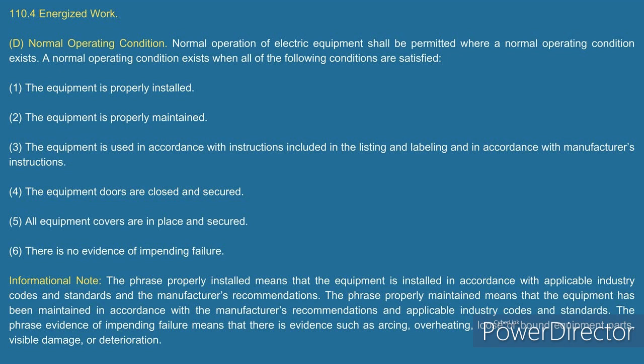But you're not opening equipment, you're not doing anything. Sure. You have to realize how serious that is. I was up in Seattle looking at the safety for Nucor Steel, and the power that was coming in before they put a really fast clearing time device on it, where it came in, it was 1,500 cal. Once they put the clearing times on there, it dropped down to like 250 something. But we could actually walk in there, and I took a picture, because it was normal operating conditions.